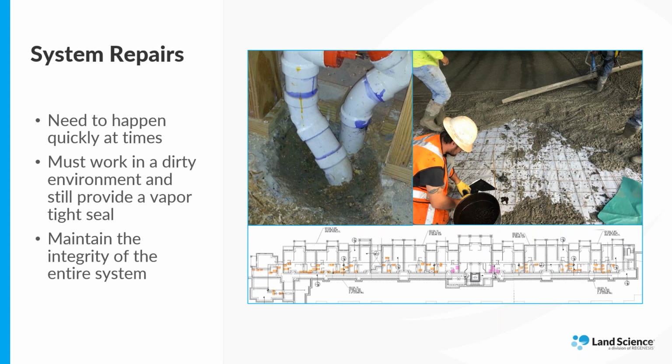And then last second repairs, even while concrete is being poured, are not typically a problem for spray applied barrier systems. As you can see from the image here, a small repair is being made while fresh concrete is literally inches away. The concrete guys on this project noticed a small cut in the barrier and communicated the issue to the superintendent, who was able to get the installer to make an emergency repair. And in this case, the installer was able to use our trowel grade material called NitroCore Detail again to completely seal up the tear so that the concrete pour could continue.